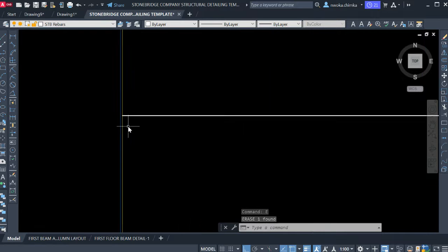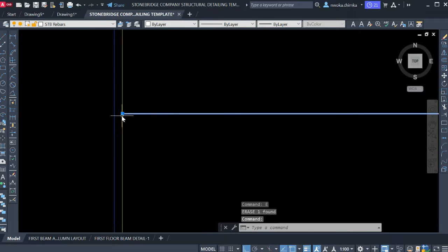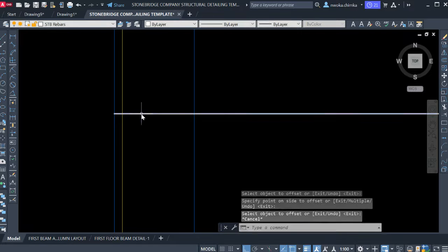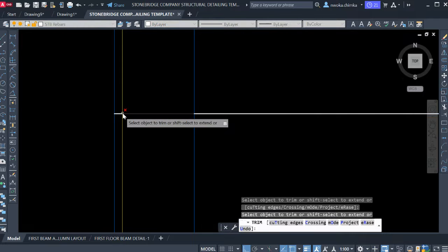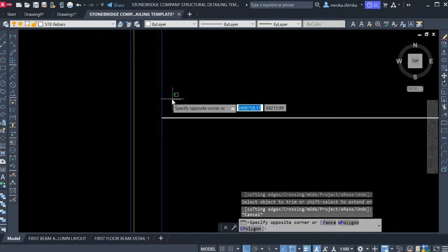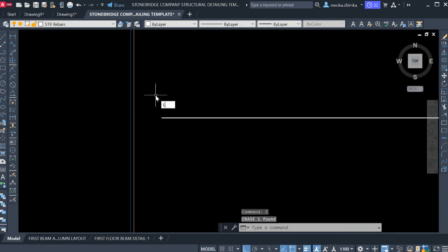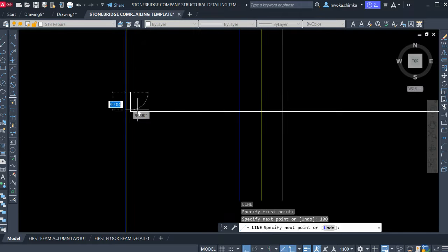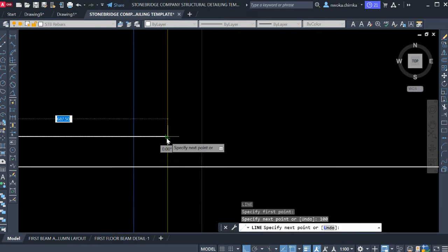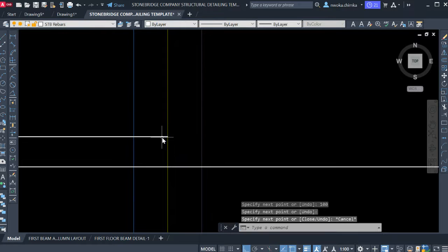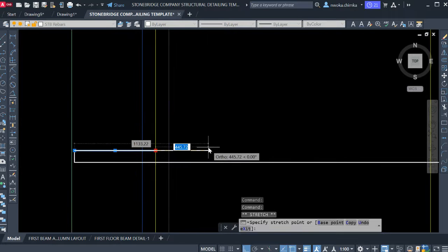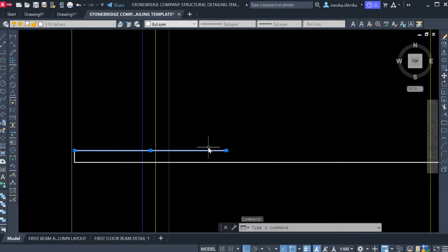And also the same thing happens here from the slab edge here. From the slab edge here, I'll offset 25 as the concrete cover, and then trim off this excess reinforcement passing this place. And then right now, I will click on line, click on this, type my bent 100, enter, and then on this place, I'll first of all click on this point, then click on this place and apply the lapping or anchor length of 600, and I'll click enter.